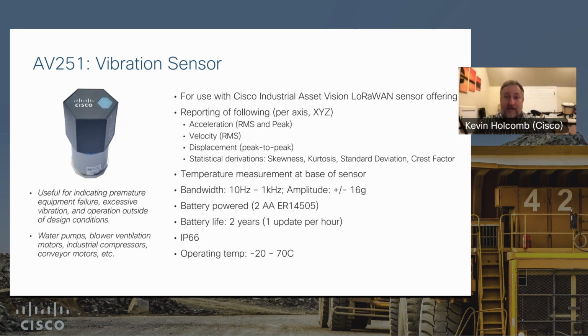It's just knowing what you put that sensor on and setting those firm thresholds there, based on an ISO spec. So another cool thing about this, it has a temperature sensor in the base, right? So you can pick up those kind of machine failures, like a lubricant gets old or it's gone and the machine starts to heat up, or a bearing gets damaged and it's causing friction and causes heat.